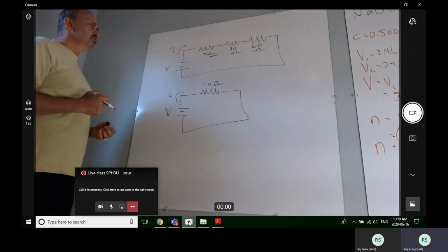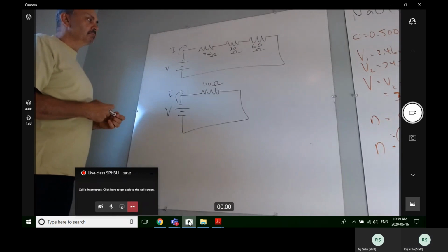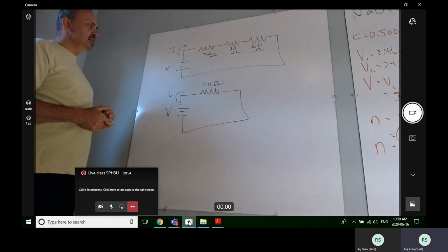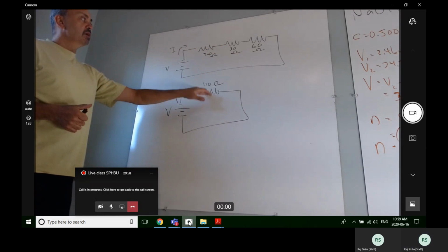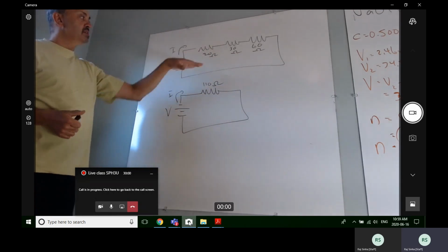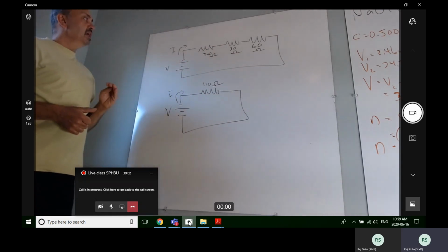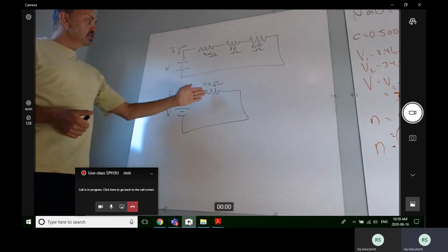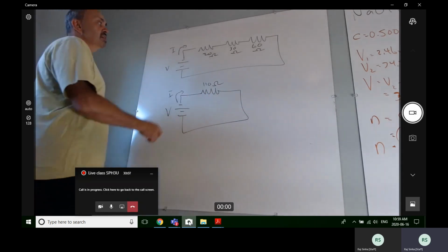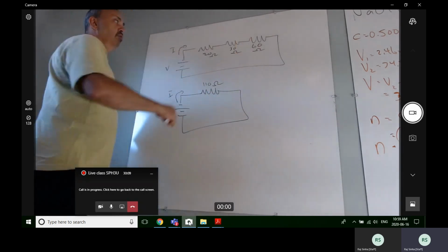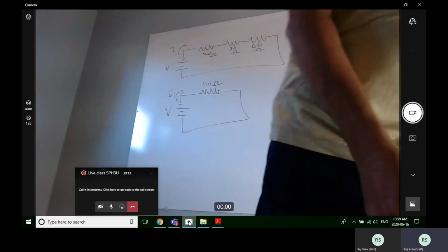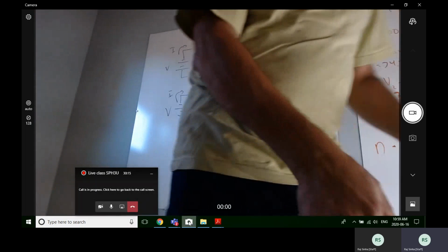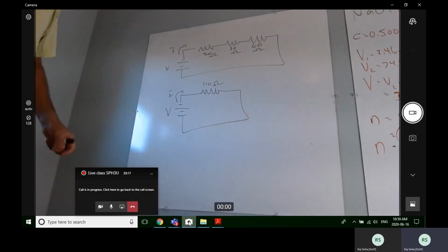Even though we could say total resistance, when I talk parallel, it's not really total. So I'm going to use equivalent resistance when I'm talking about these resistors, and these three are the same as this. So this circuit will have basically the same general properties, having to use the same amount of voltage across 110 ohms as I did here across these 110 ohms. Okay, so there's the first one. The second one says if I have an 8, 6, and 48 in parallel.